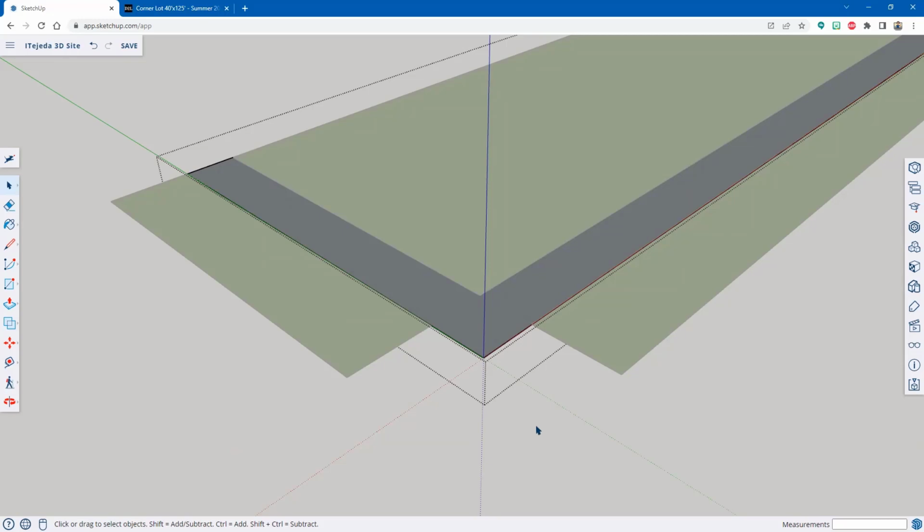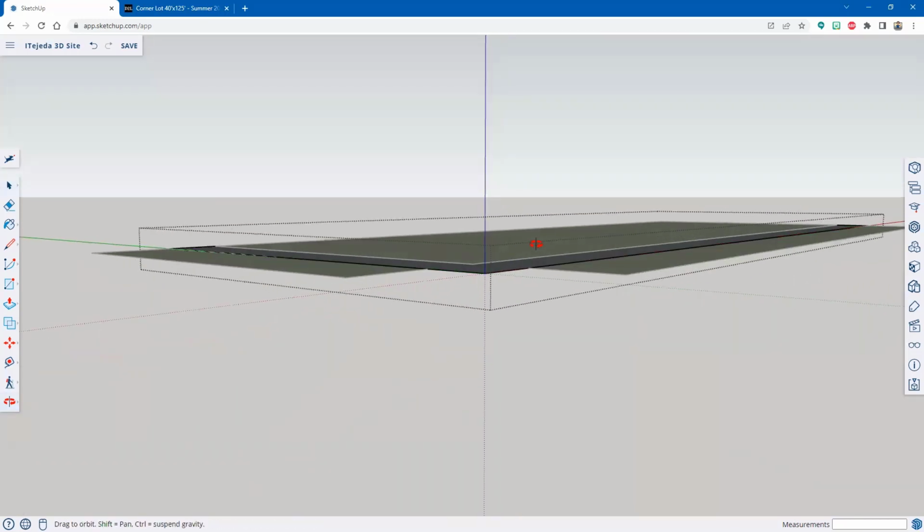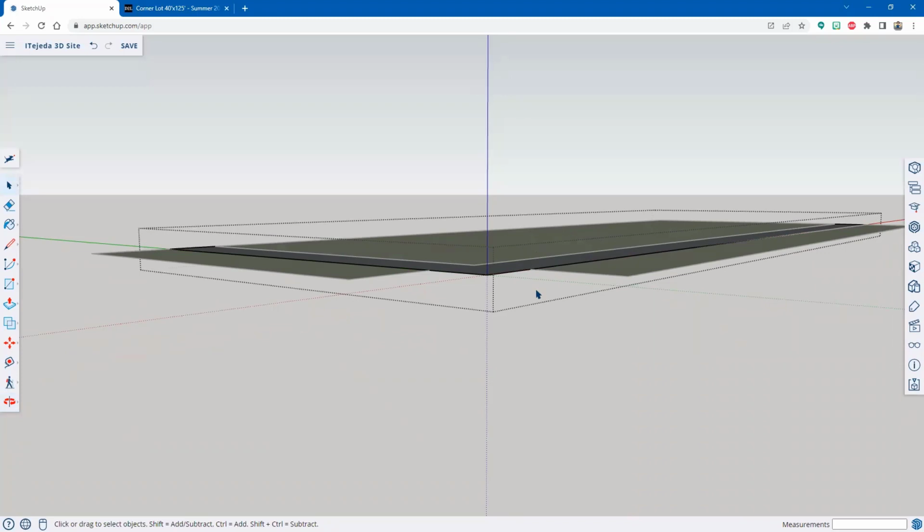And then this dashed line shows up and it's a boundary and it's kind of saying, look, you've selected this whole group and this is the extent of that group. It's being defined by the dashed lines that show the extent along the green axis, along the red axis, and along the blue axis. So I go, okay, I'm editing the group. That's what I needed to know. So that's a good visual cue.